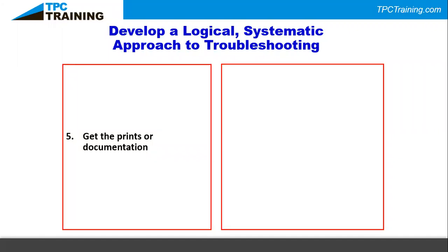There is a thing called a category of an electrical meter that's super important for electrical troubleshooters to know, whether it be category 1 all the way up to category 4. And we talk about that more in depth in some of our electrical troubleshooting courses on making sure you have the right category, right voltage rating, and proper listing by a third party to make that work.